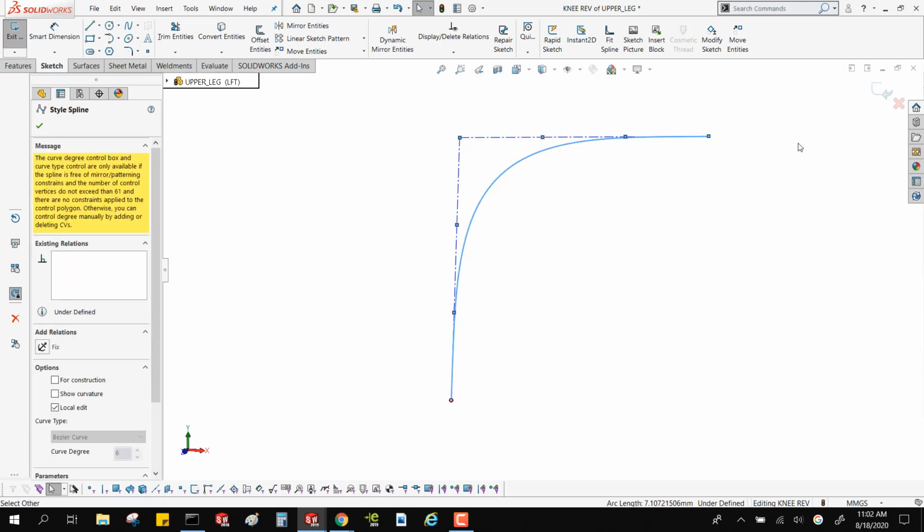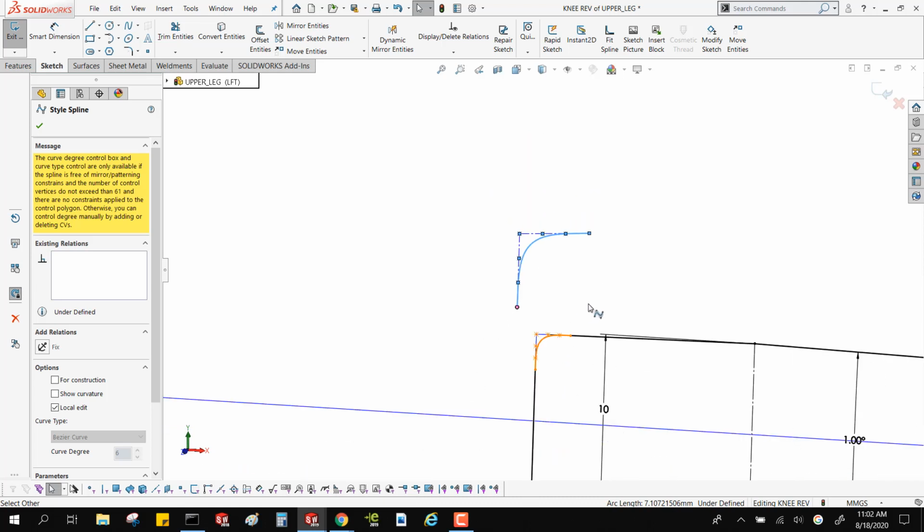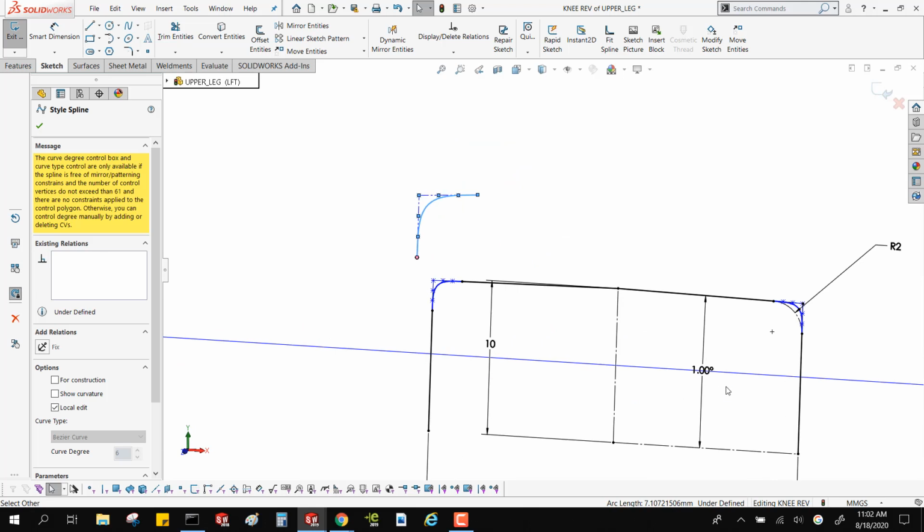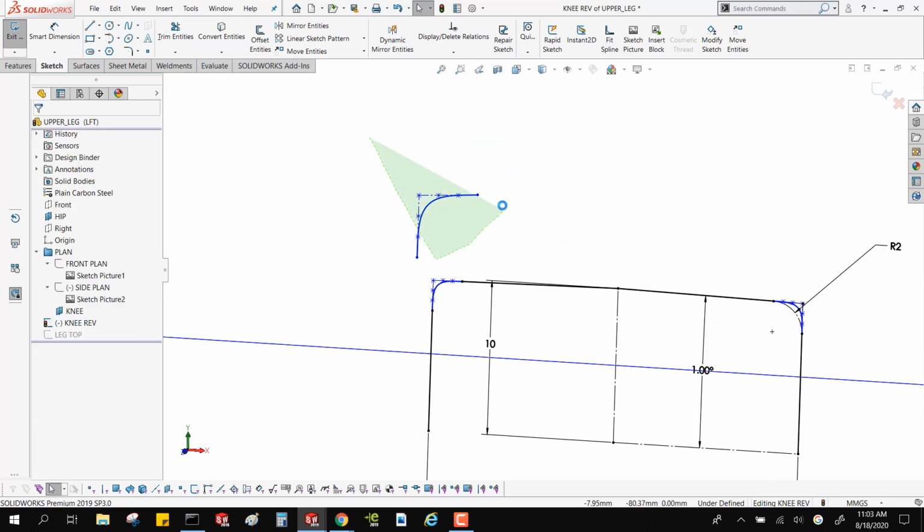So now I've got a corner that gradually goes from one to the other with a perfect curve, where I can set this up to be collinear with the other edges that it's coming in contact with. In this one, I've actually got this thing with draft. Again, if you're building a part that is going to be injection molded, you want to make sure that it can come out of the cast, or out of the injection mold.